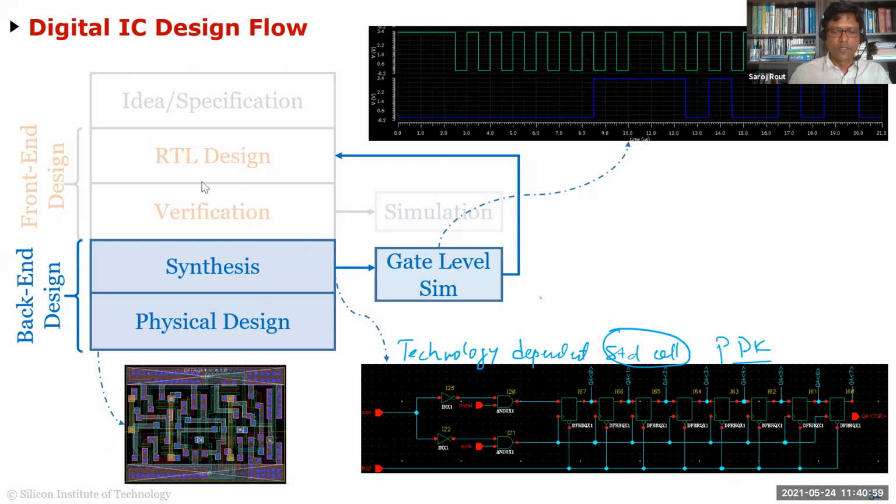Okay. So just make sure you understand, in custom design, when I was doing design from circuit design to layout, it's all manual. There is no automation there. If I have designed an amplifier, I pretty much design the entire layout by hand, in the sense that I have to place the devices and route them, by hand meaning using the CAD tools to do it. Whereas going from behavioral to synthesis and synthesis to physical design is all automated in the semi-custom flow.